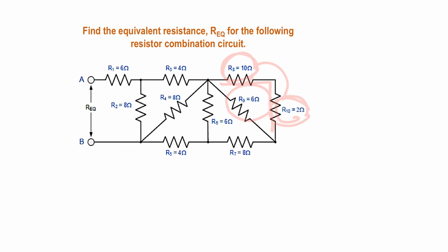Once you combine, in the drawing the combination is going to be in a vertical position. For example, if I draw for the 10 and 2, 10 and 2 is basically in series, so I'm redrawing only this part. I'm going to get the combination in vertical. That's the method to solve the arrangement of series and parallel for a diamond shape.